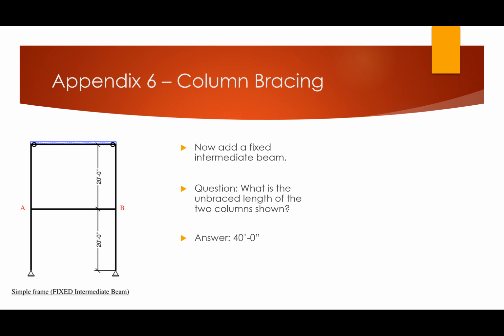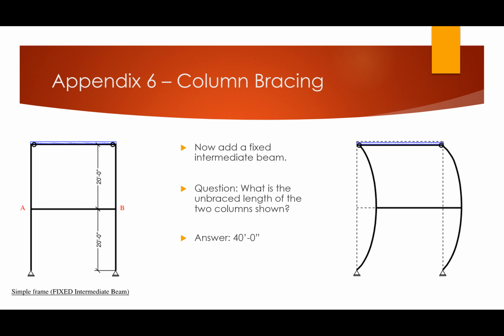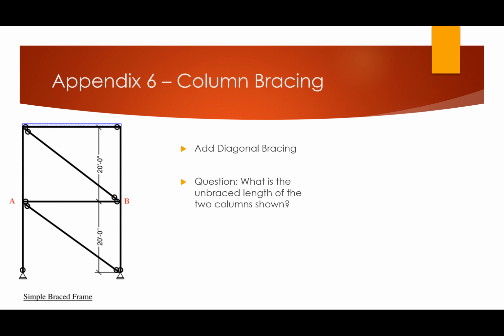This is not going to meet Appendix 6 provisions, and you get the exact same buckled shape, so that does not help you. Well, okay, one more. What if we add diagonal bracing to this? What's the unbraced length then? It turns out here, the answer is 20 feet.